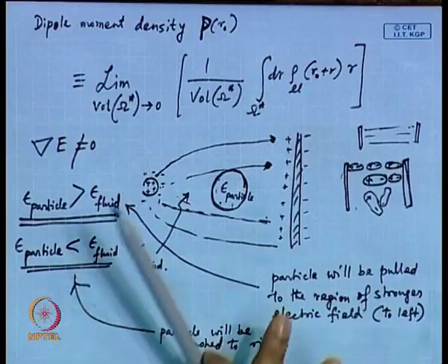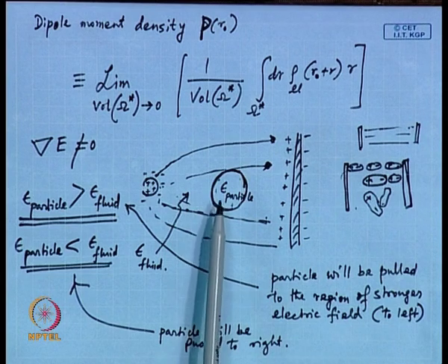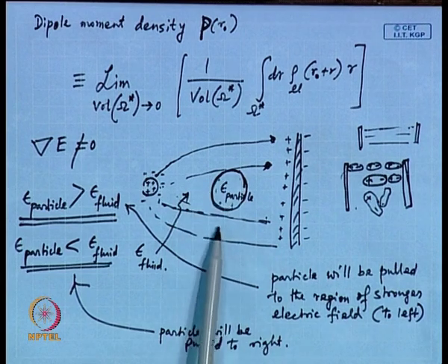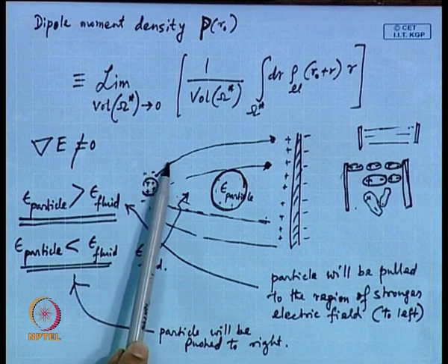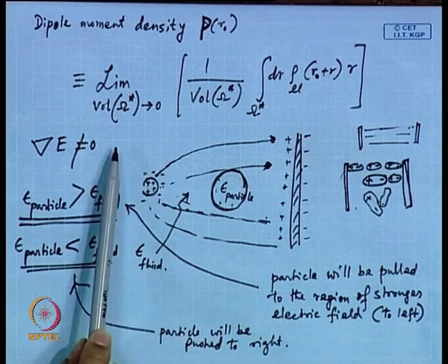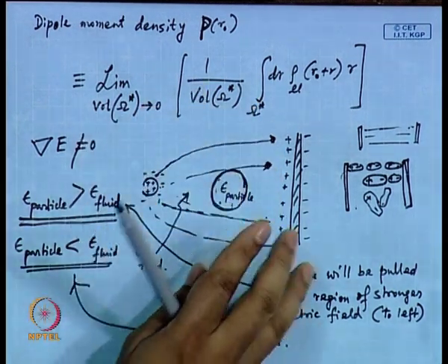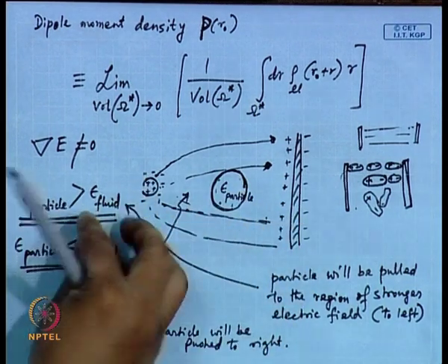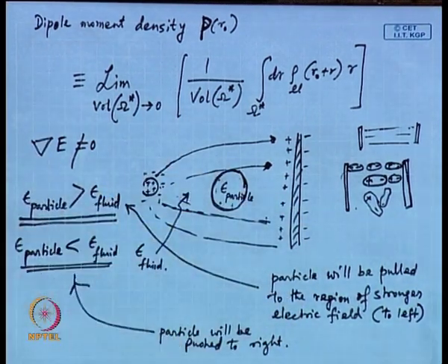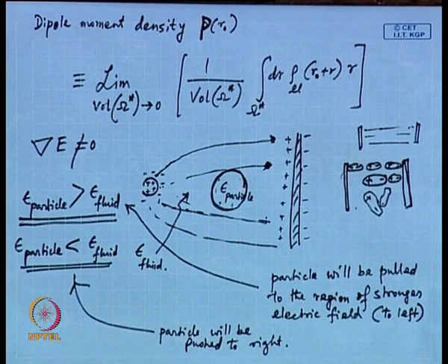The other possibility is the DEP trap that I said, that you trap the particle. Suppose so many particles are flowing through this, but some particles satisfy this condition, and those particles will be trapped next to the electrode. Suppose you have a sample, a slug, and you flow the slug through this place, and whatever particles within the slug satisfy this condition, you trap them next to the point electrode. This is referred to as the DEP trap.